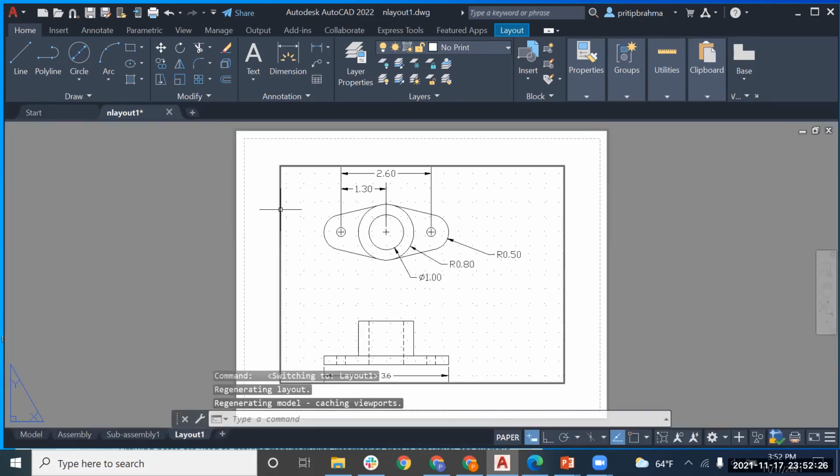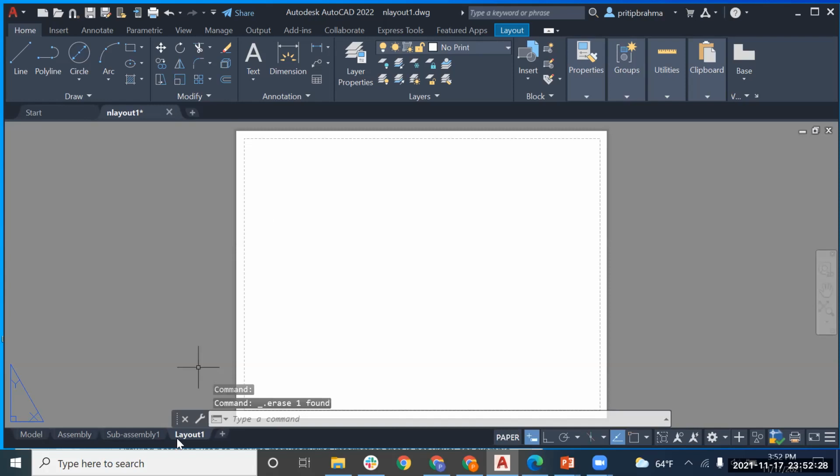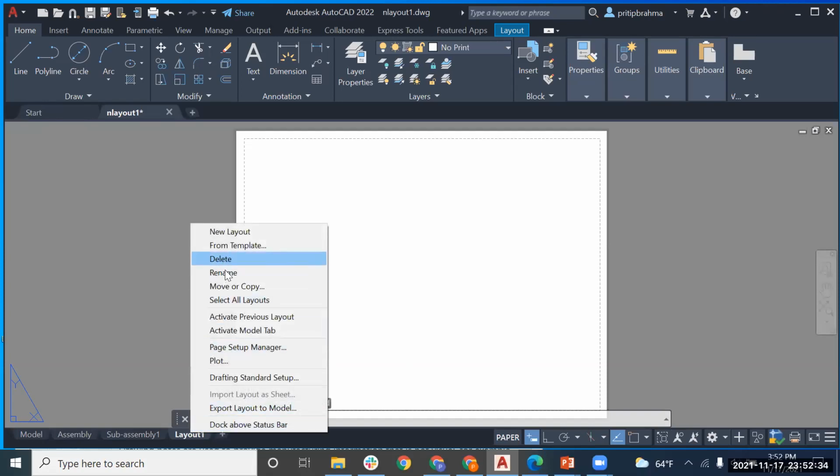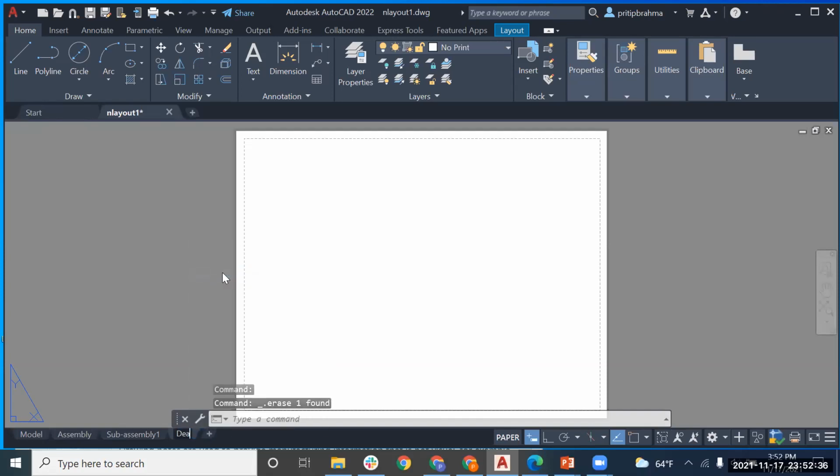See, that's the generic window that pops up. Delete that, because that's probably not what you're going to use. And then you can rename this as, I don't know, you could give it your actual part name, but detail number one. So you can keep adding pages here and have a full set of drawings you've put together, and then you can batch plot so that they all come together in one book.